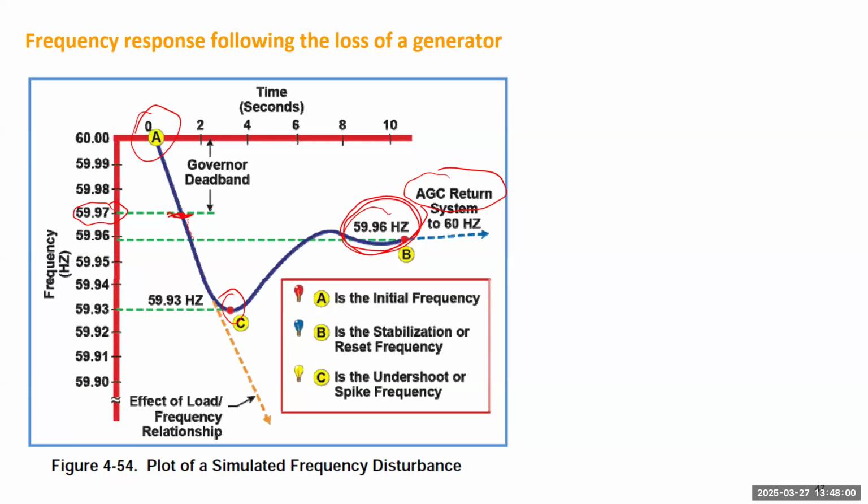So how do we estimate this slope? That can be a very important problem, especially for today's power system. You have a lot of renewables, right? When you use renewables to replace conventional generation or take care of the load, those renewables don't have inertia. Either they don't have any inertia, or their inertia is not directly affecting the grid. Like a solar farm, they don't have inertia; they don't have a rotating part. A wind farm has inertia, but it is connected through power electronics, so you don't really see that much inertia.